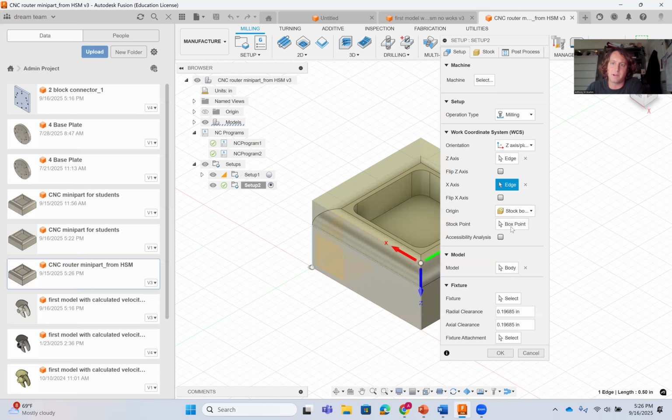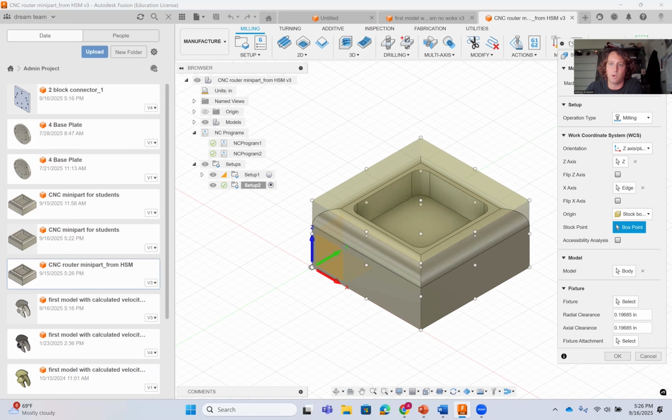But again, I'm gonna select the point at this lower point there, and then we're gonna make the z-axis. So I'm going to select the z-axis going up. There we go. And then we're also going to select the x-axis going this way. All right. And then it's going to have us reselect that point there. So this is also the correct orientation that we would want.